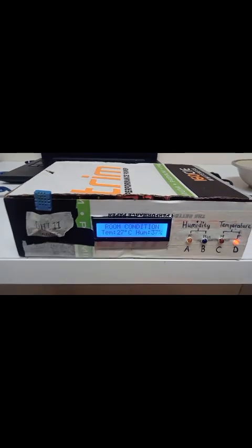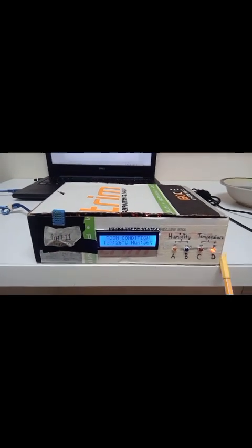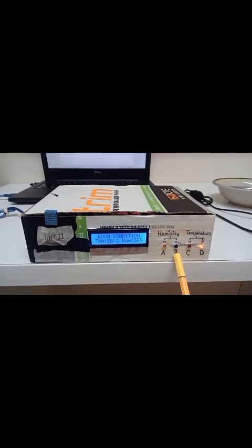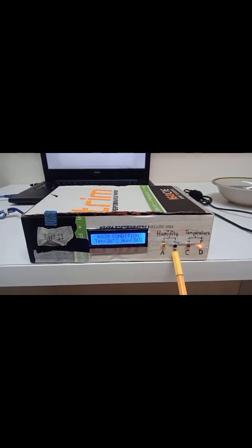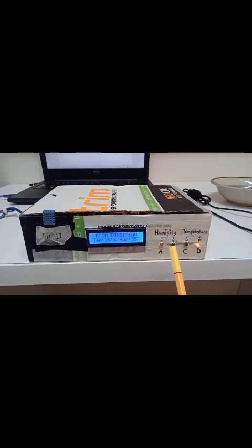Here is our integrated circuit. You can see here is our LCD, our DHT sensor, and our LEDs to indicate when the system is activated. A will be representing the humidity fan, which will kick in when the humidity is above 55. And B is our humidifier, which is the moist sprinkler, and it would kick in if the humidity is below 35.